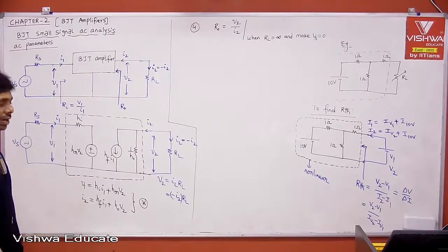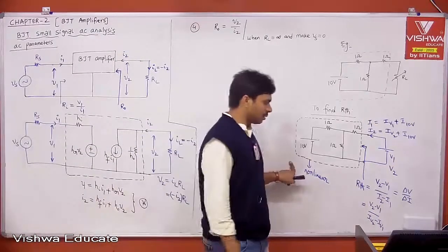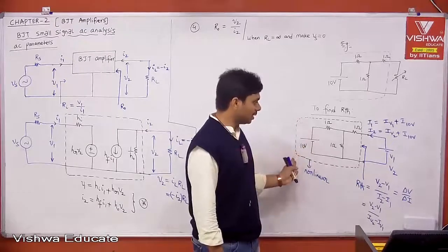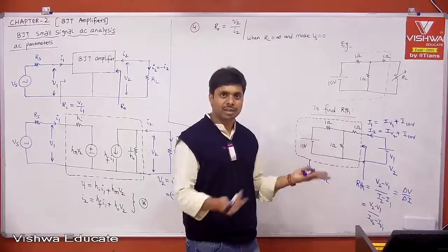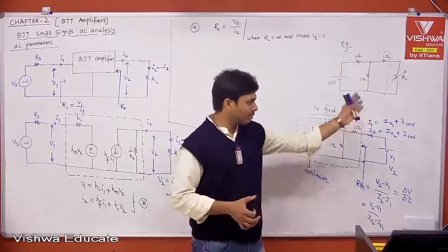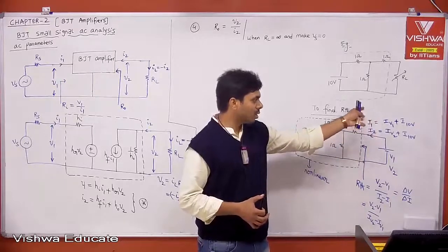I think so many definitions that I defined till now are satisfied. For a non-linear network, we have to take dynamic resistance. By shorting it, it becomes linear. Then you can go ahead with the static definition. That is your Thevenin methodology. And why go with the dynamic resistance? To cancel out the common quantity in the output currents.